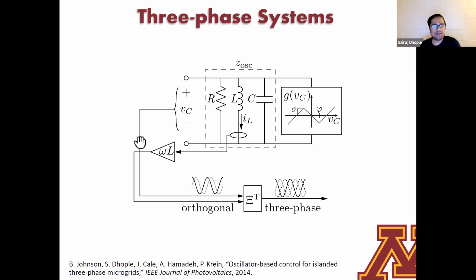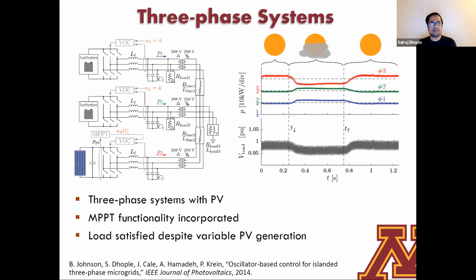So what you can do is take these two waveforms and run them through a simple transformation, an alpha beta to ABC transformation. Then, starting from waveforms that are 90 degrees apart, you can generate three-phase waveforms that you can then use to close the loop on a three-phase inverter, right? These three-phase waveforms can then be utilized in your PWM switching scheme appropriately. Here's a very simple setup that illustrates this.